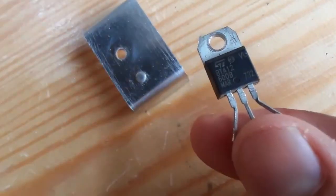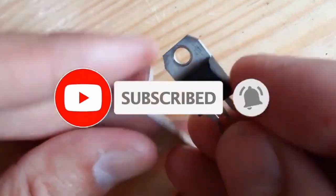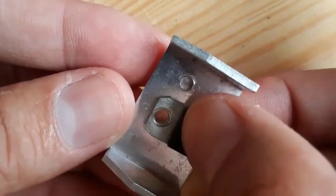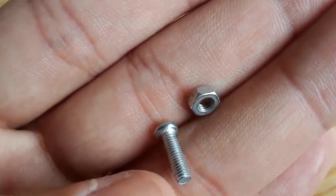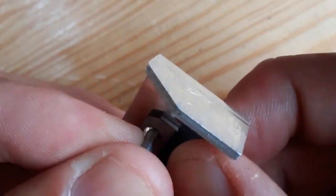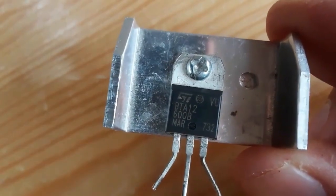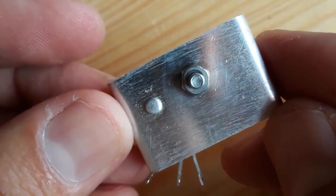Now, as you can see, every TRIAC should be connected to its heatsink because it releases heat. It gets very hot. That's why you should always pay attention. If you have a TRIAC with a heatsink, you should always use the heatsink. If you ignore the heatsink, the TRIAC can be damaged because it gets hot. Okay? As you can see, the TRIAC is now connected to the heatsink.